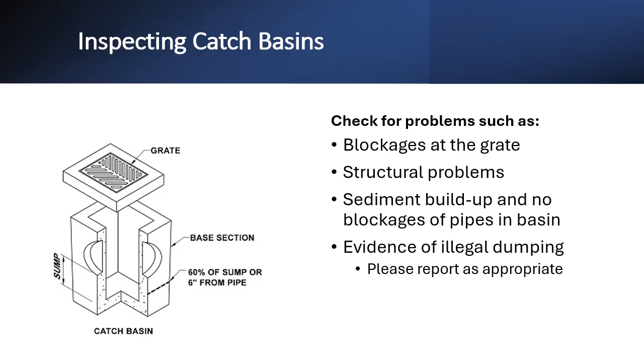There should be no structural problems at the inlet or curbs, including any damage, settling, or misalignment that could disrupt its function. There should be no sediment buildup in the catch basin sump. Sediment should be no more than 6 inches from the outlet pipe.